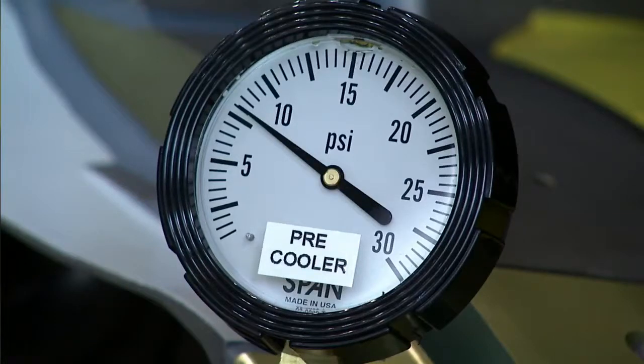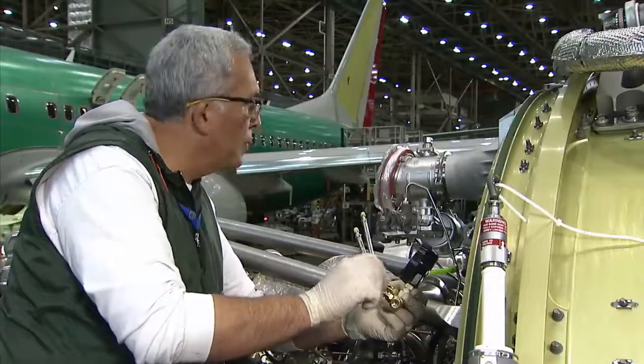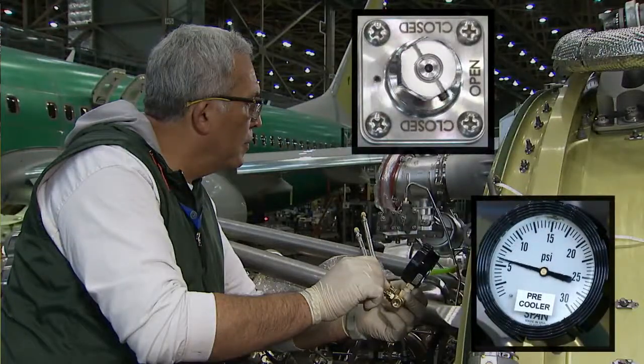With good control pressure, you can use the needle valve on the test assembly to simulate the venting action of the 390 sensor. While you observe the control pressure, also observe the PCCV to see if it opens per the aircraft maintenance manual. If the PCCV does not open according to the AMM requirement, you must replace the PCCV. Note that for the sake of this test, if the PCCV opens to within 30 degrees of fully open, it is considered opened. A good reference to use is the inside of the screw head on the valve housing.